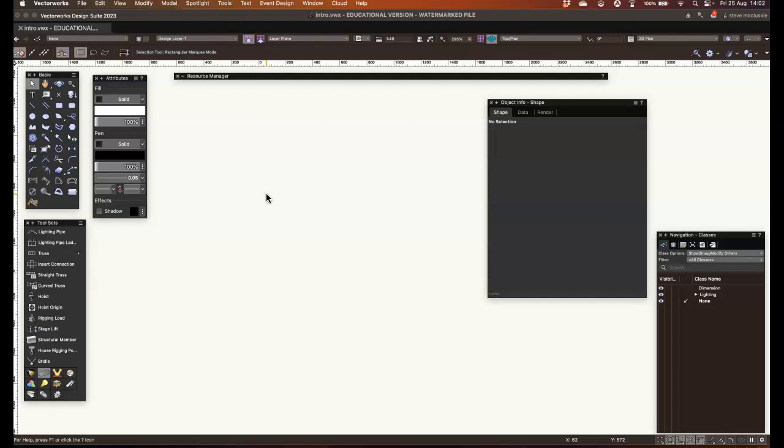Much better to take your time and do the accurate set plan with spacings, marking out areas off stage for storage, marking out fire exits and things, all in a line drawing rather than taking ages to do it in a 3D thing, which is inaccurate. And actually, if all you need to do is mark out fire exit spacings or stage storage or masking positions, it might only need lines initially in order to plan things out. Once things have been worked out, then maybe you turn it into 3D, but lines are your friend.